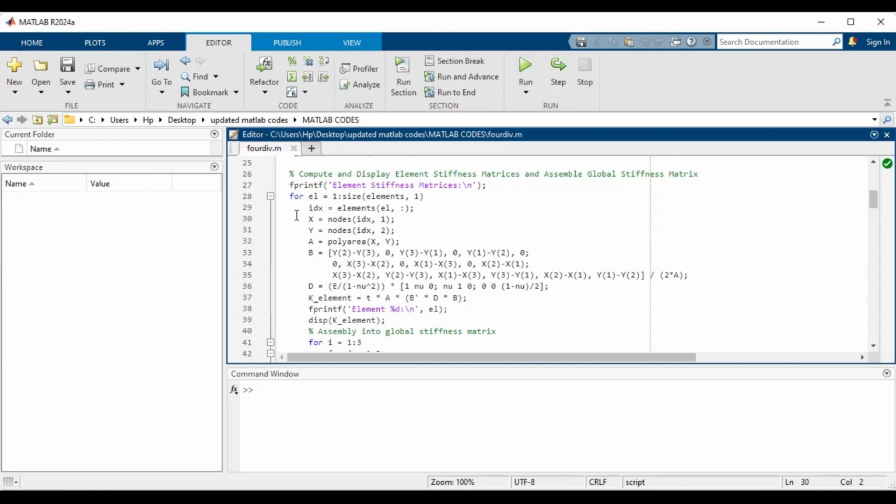So you can define your cycle. Yeah, you want to run this calculation. I want you to do this same calculation for me, like maybe say 5 times. I want you to do the same calculation for me, let me say 10 times. So you create a loop so that it goes through that thing based on the number of times you specified. So here we have to create a loop to compute our elemental stiffnesses. Remember, we divided the plate into 4 and we are having 4 elements. So we are creating a loop that solves for the elemental stiffness 4 times.